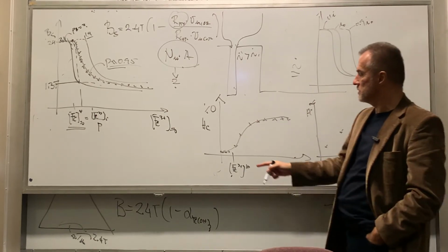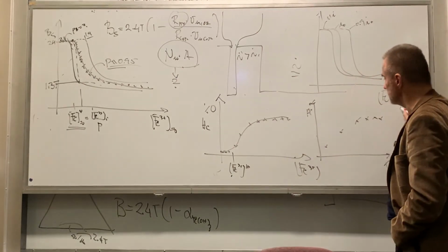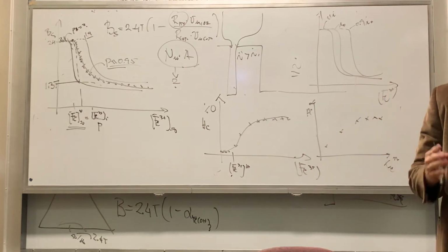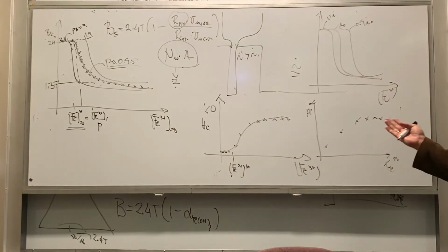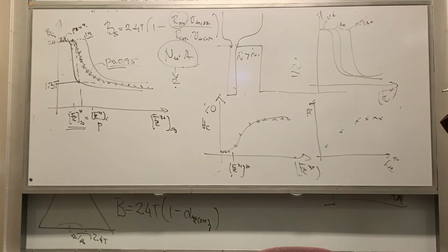And if you plot coercivity versus oxygen content, for example, it will show you some other thing. But what you're really doing this way is having a quality control over your deposit in terms of the magnetic moment and coercivity, which are two most important parameters when it comes to soft magnetic alloys, assuming that your composition and everything else is taken care of according to the process. And so with this,